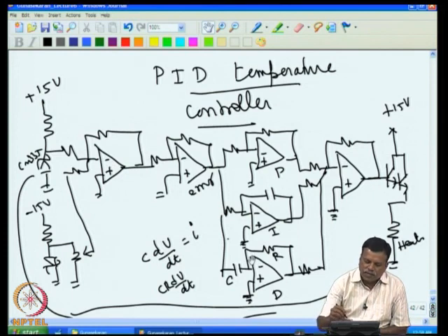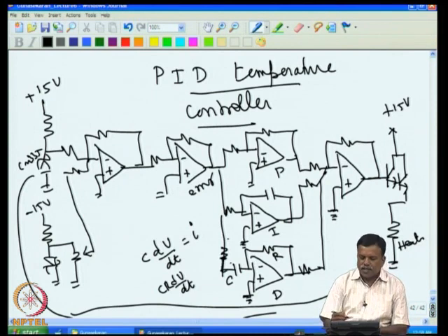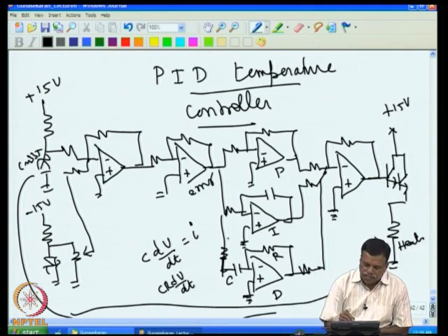In addition to that, we also do one more protection, so that we don't want the system to respond for all the frequencies. If there is a very low frequency change, that will not produce too large a current flow; the current flow will be limited by this resistance.